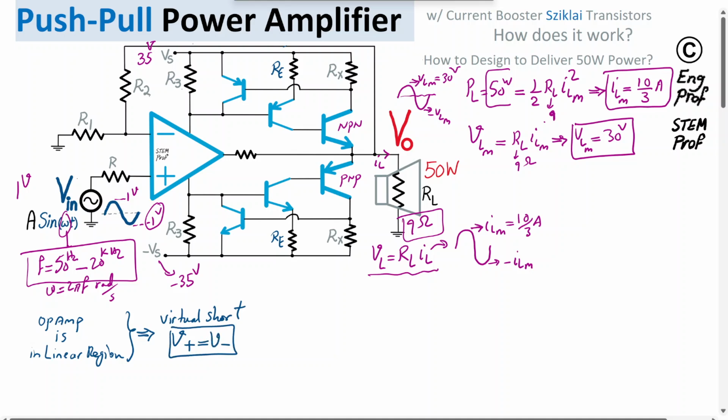So if at the positive terminal we have Vin, and for a good op amp we can assume that practically the input current is 0, we don't care about this resistor R, there is no voltage drop, it's just there for impedance matching. This Vin appears exactly at the positive terminal, and because of the virtual short, the op amp with negative feedback enforces that Vin also appears at the negative terminal as well.